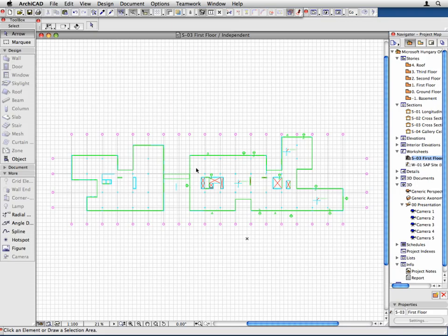The DWG file has been imported to ArchiCAD and placed on the worksheet. The structural engineer uses the same origin in AutoCAD, so the contents of the DWG will be placed back to their original position. Zoom out to see the entire drawing on the worksheet.